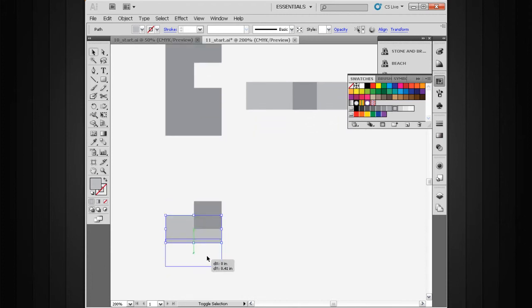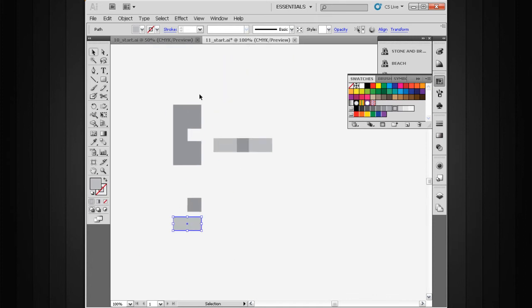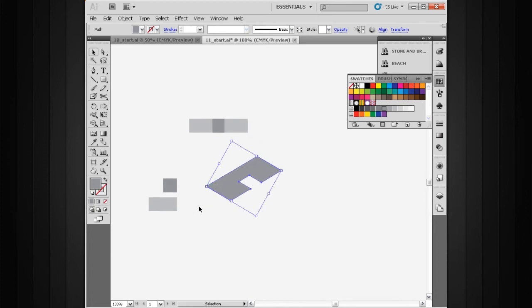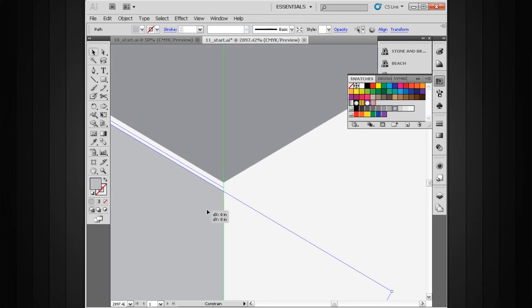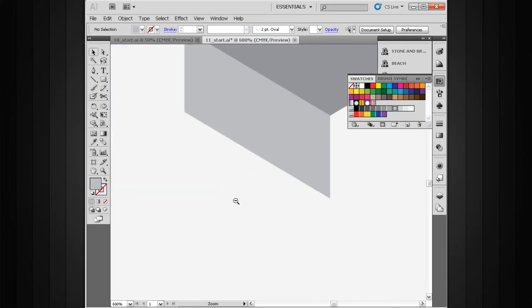And I tell you what, let's put this building together by running our actions. I'm going to run my top action on this shape. Now remember, we had that keyboard shortcut set up to F6. That's the top clockwise action. And let's focus on this left side first. This is the shape we need, so we're going to run that left action with F5. Snap that one into position here. Get in real nice and close there so we can get those two shapes perfectly snugged up together.